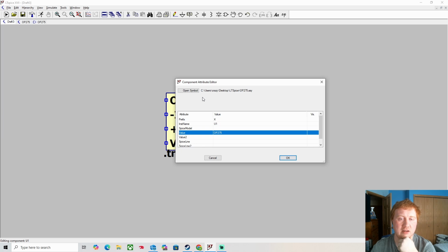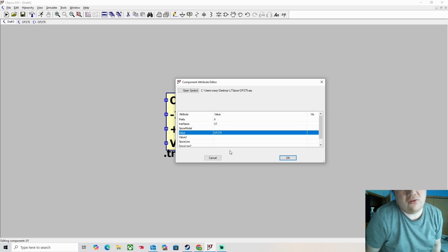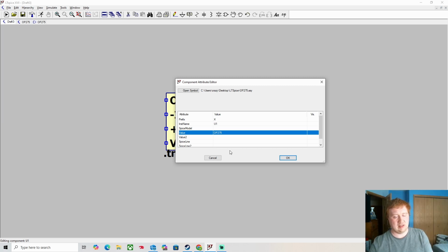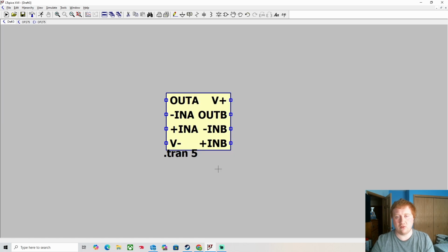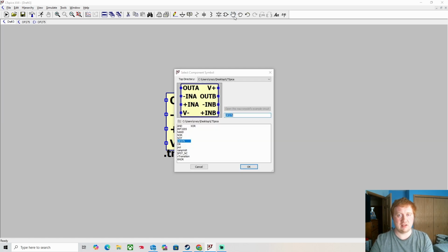We've got a symbol and everything. It doesn't know the circuitry in it without the lib file. It's like it's referring a null circuit. So that's why we need that spice command.